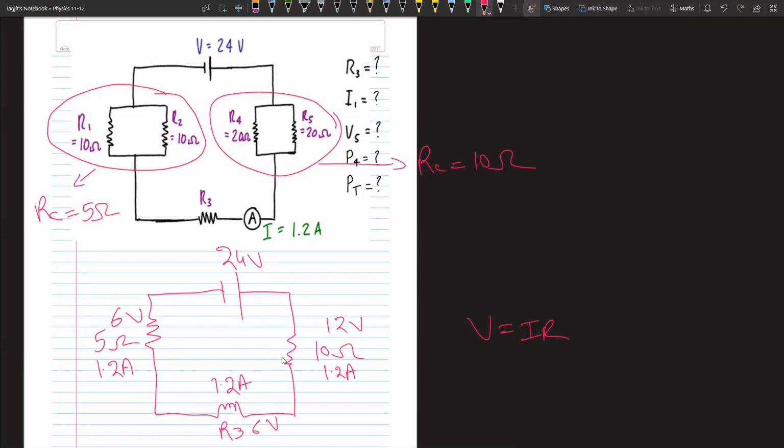Okay, so we have, for example, the 12 volts is for the combination of both of them, right? That we added. That's right. Yeah, combined. But I've drawn this as a combined resistor. But now this is a series circuit. So technically, this 12 volt that I found is 12 volt here, and the same 12 volt is here, because the parallel ones are going to have the same voltage. And that means we have 6 volt here. So there will be 6 volt on this, because parallel resistors get the same voltage.